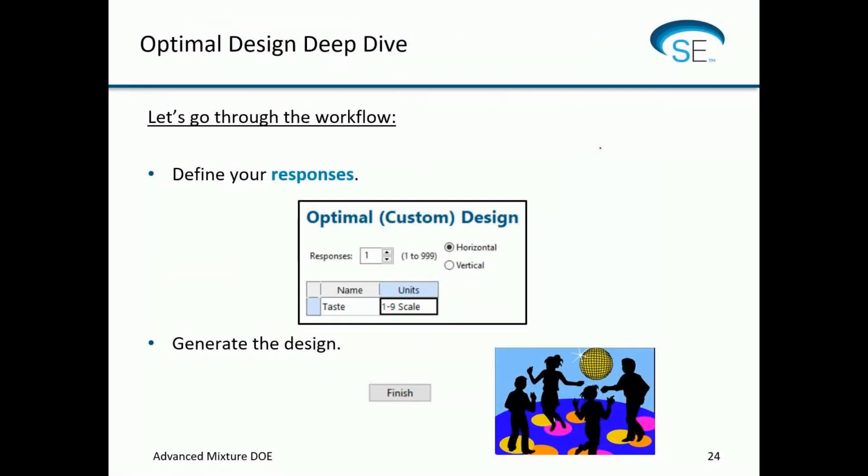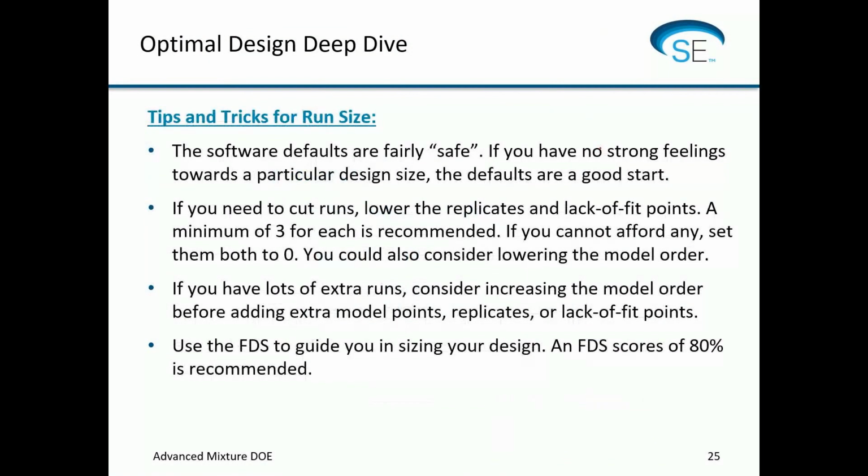Okay. So tips and tricks for run size. The software defaults here are fairly safe. If you just go ahead and spam click continue throughout, you'll get, I think, a fairly safe design, meaning it's not too big, not too small. If you have no strong feelings towards a particular design size, the defaults, I think, are a good place to start.